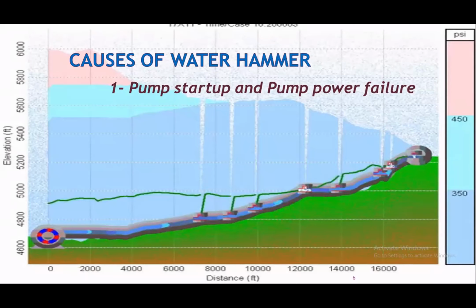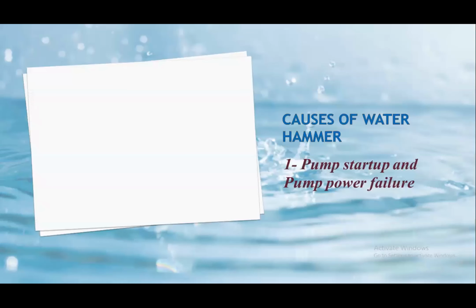That indication is that the flow or the water is turning into vapor, okay? Well, what will happen when we return the power and the pump starts up? There is a very famous phenomenon that is combined with this process of pump power failure and pump power startup, and it's called column separation.